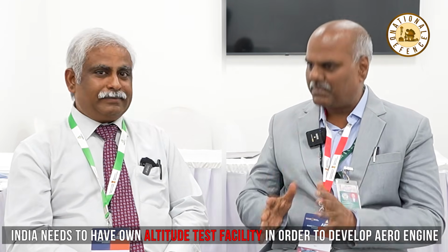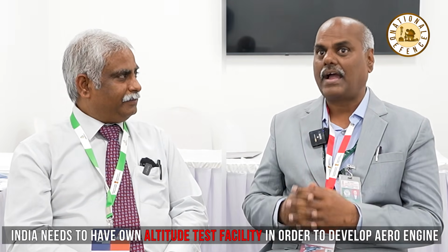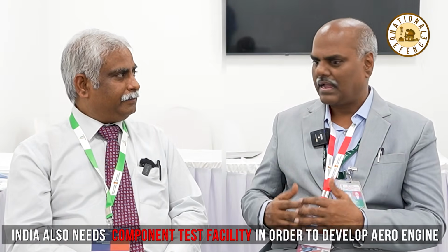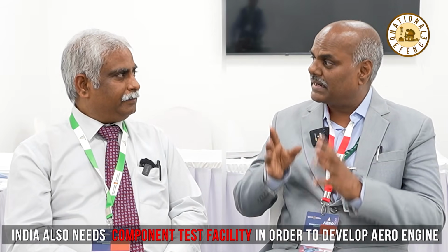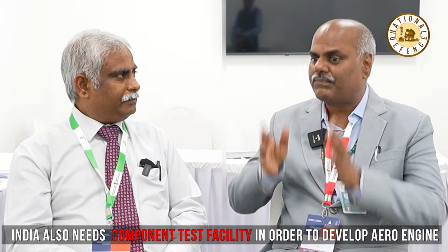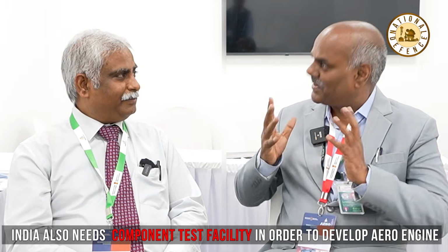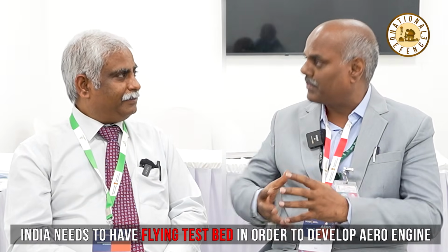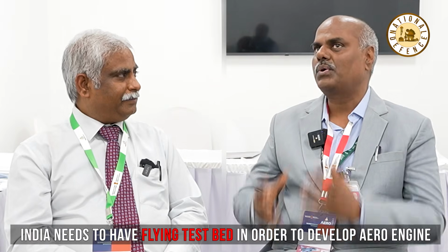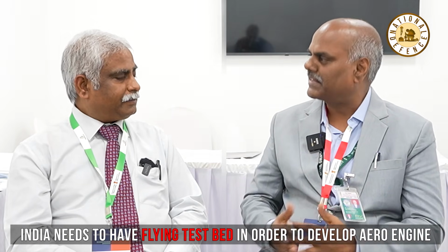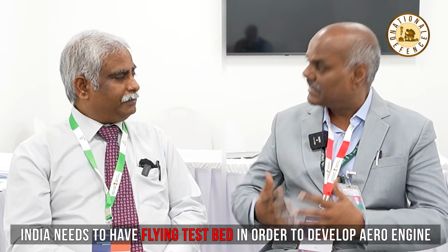So establishing altitude testing and component test facilities. Say for example, what I said, turbine, at the actual condition, it will be developing almost like 35 megawatt. Can you imagine? Okay, so that has to be tested. So high temperature air with that absorbing power, we call dynamometer, should be available. So altitude testing, flying test bed and component testing is a must.